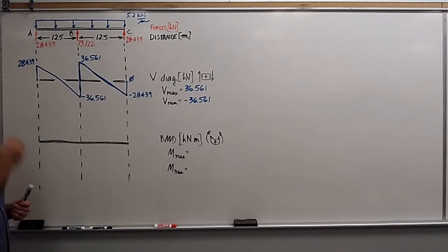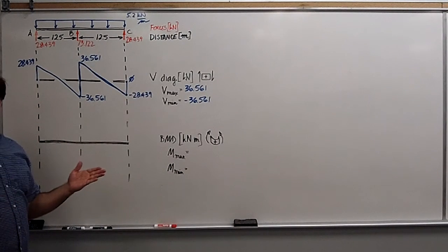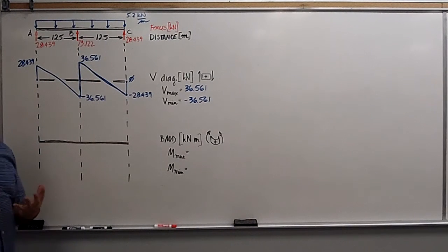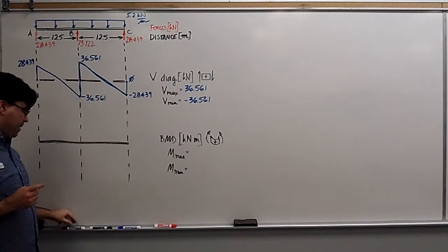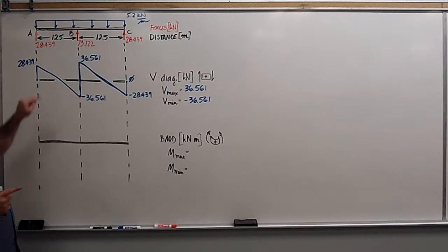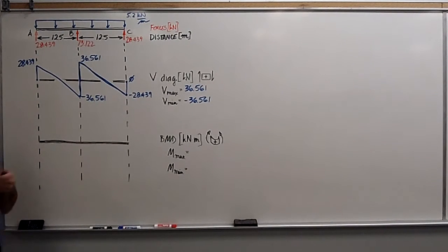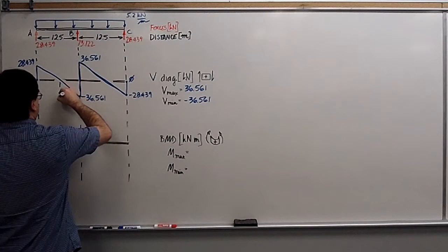Okay. In order to move on then to the bending moment diagram, areas, remember that? So we have 4 areas here, 4 different triangles. One thing before we forget is to remember that wherever the shear diagram passes 0, we drop another line for the bending moment diagram.